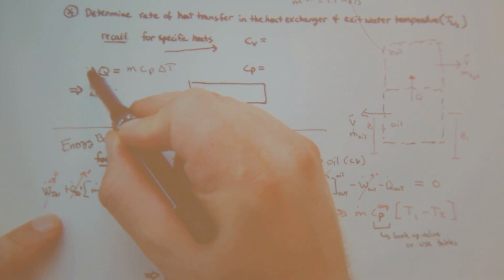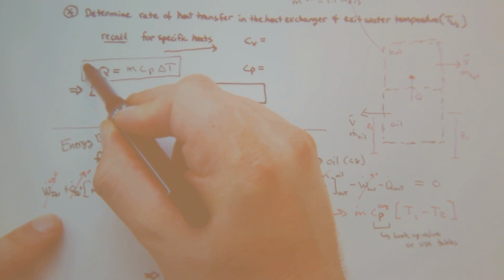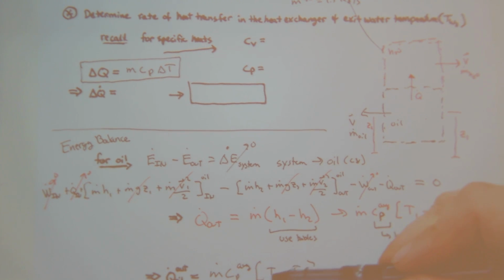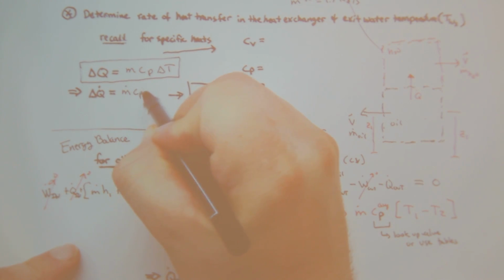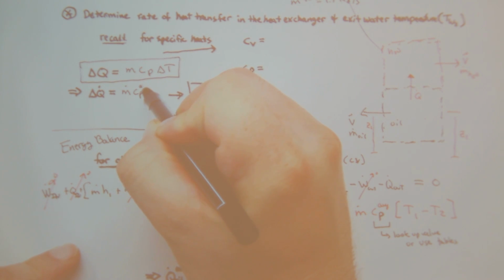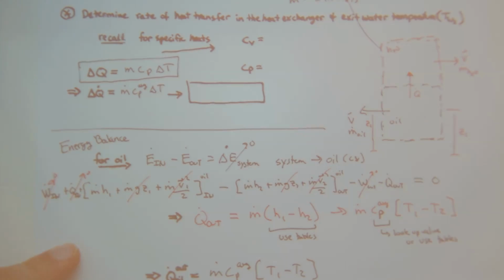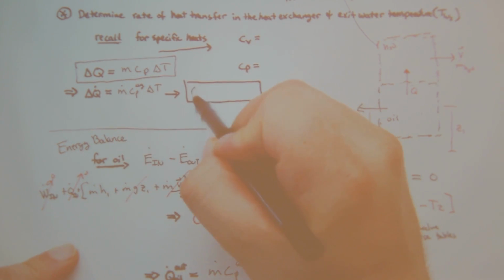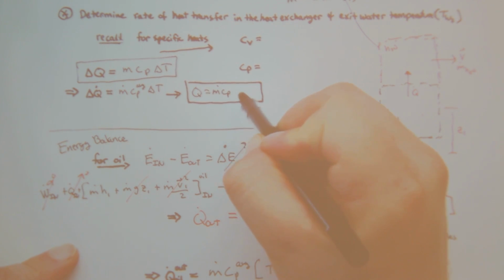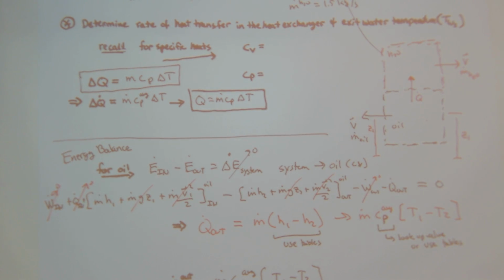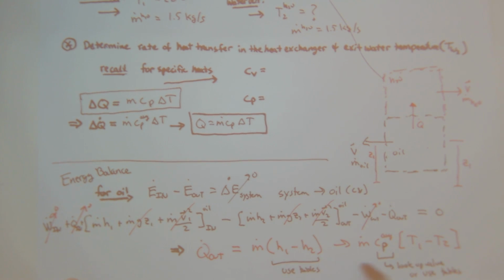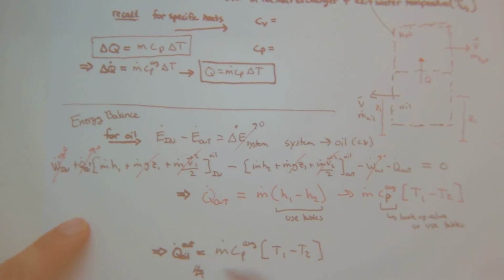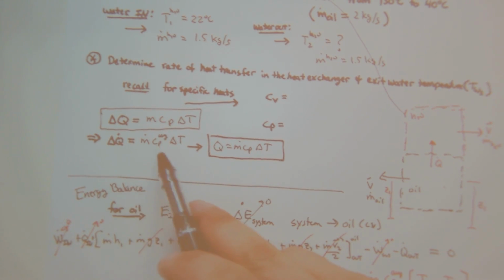So this is freshman physics. And we basically did the same thing here, but now we have dots, but of course I can do this, so I have some m dot Cp. And here I have a delta rate, so I can just do Q dot equals m dot Cp delta T. So I use this formalism to get this expression. Here I went from freshman physics and just put it in rate form.